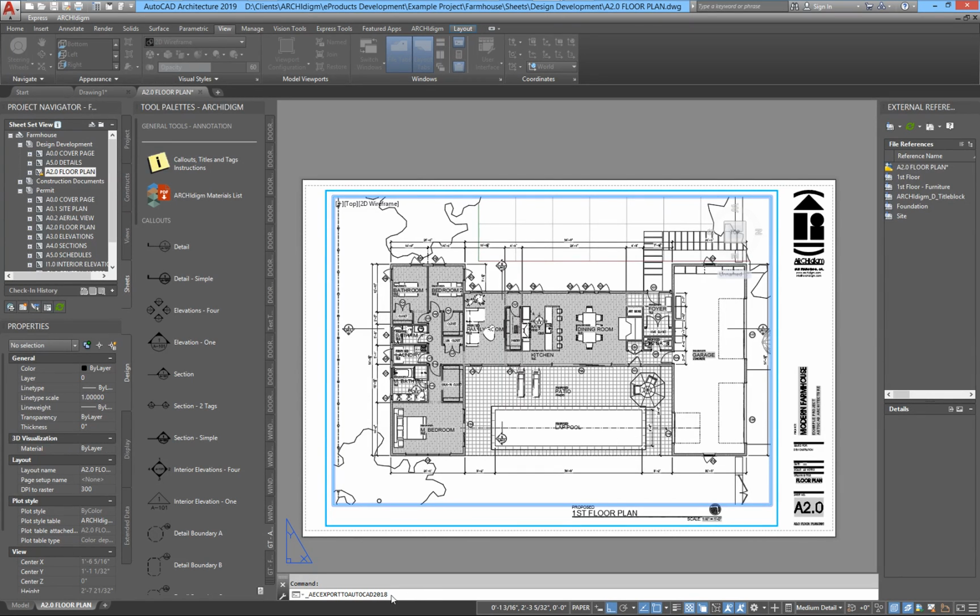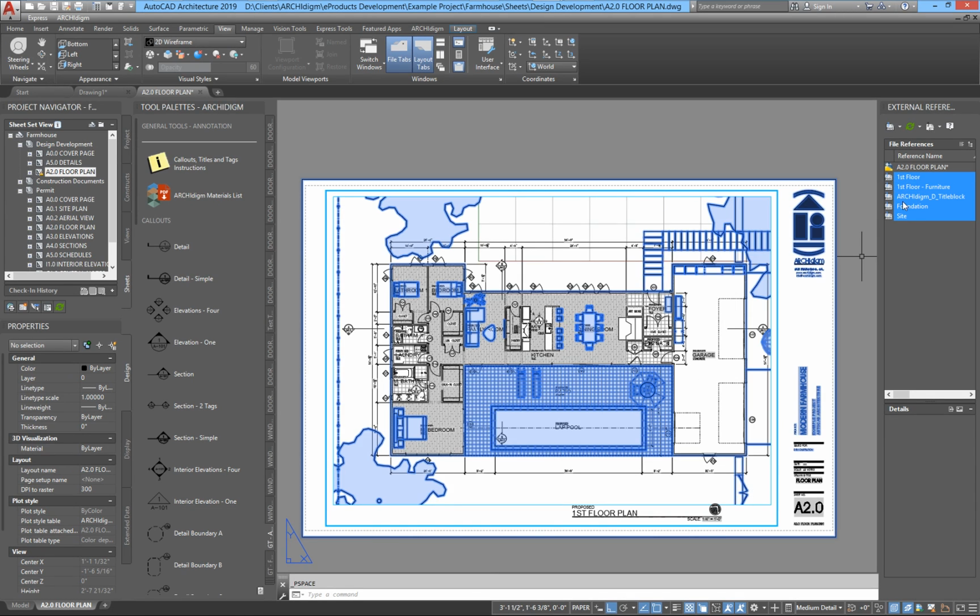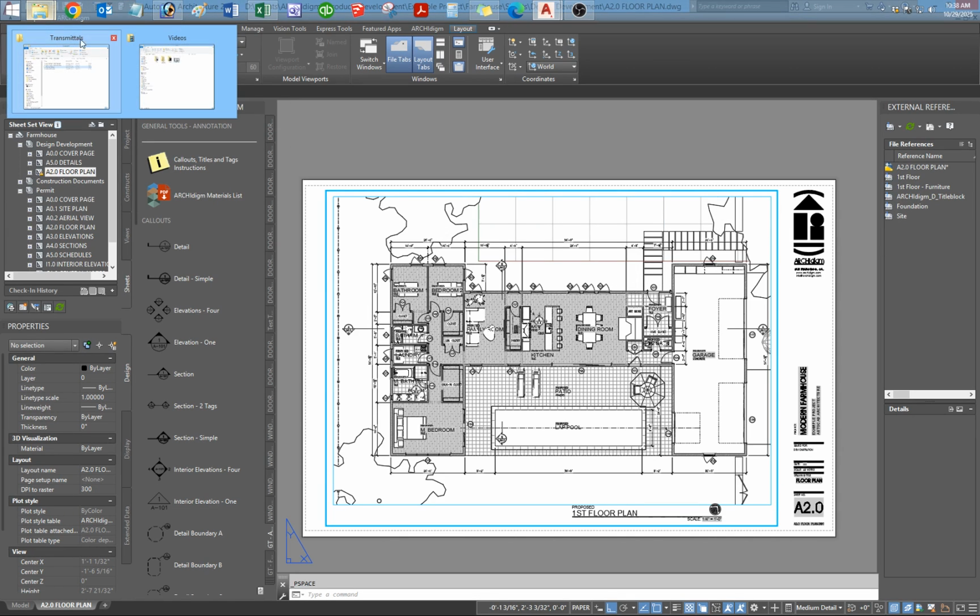It should take a few seconds to a minute or so to do all of that conversion work. If it goes really fast, just a split second or even a partial of a second, that usually indicates that it won't convert it. There are a number of reasons why it won't do it. I have found that if you take all of your XREFs and bind them, sometimes that creates a problem where it just refuses to do it. The binding has actually occurred in this process, and I'm going to show you where that binding comes from. But first I want to open the file and show you the product of that work.